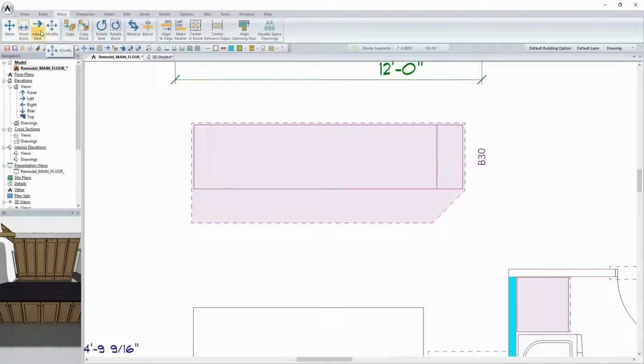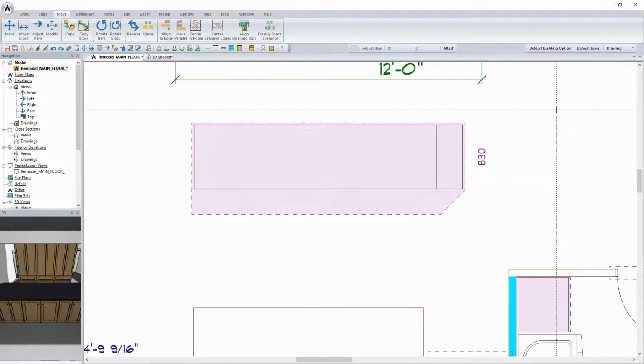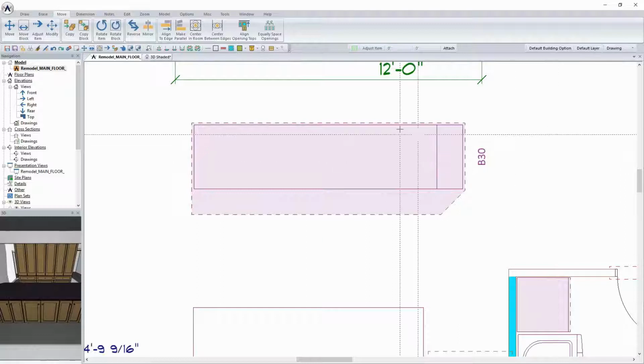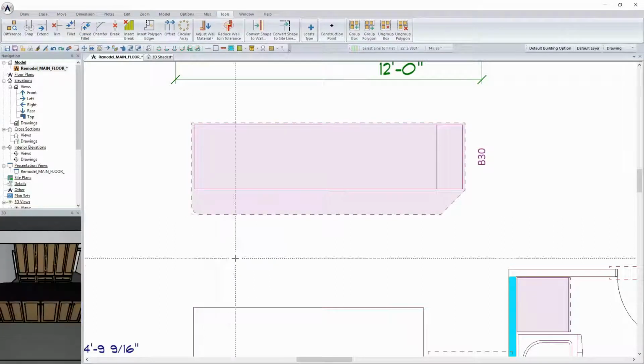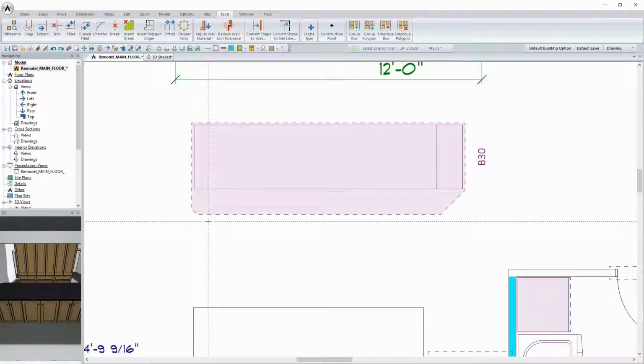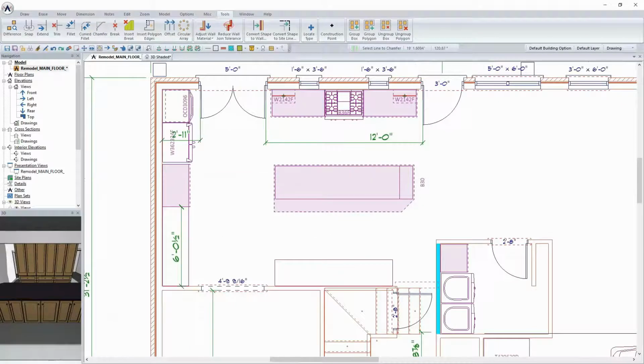I can use the adjust feature to adjust that overhang if I want it less than what it is, and so I've now set it to 12 inches, just by adjusting it back by 4 inches, okay? Corners can be curved, chamfers can be done, all using the tools, and you can come in and use the different fillets, okay? So if I wanted to curve this corner, I could come in and just curve that by 4 inches, and that just takes that sharp corner off altogether, okay? It was left that way, so I'm going to put it back, but I could also have come in and used the chamfer tool to create the same thing that I did down on this corner down here, whereby you actually get a specific dimension as opposed to the way I did it where I just simply traced it in. Okay, so hopefully that makes some sense there.